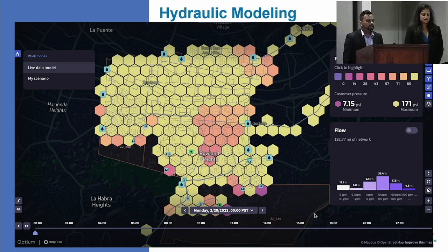So basically, first we don't even touch the actual SCADA system. We have a software that integrates to the historian, and we talk to you guys and check which tags have only read access and are not controllable. All these basic parameters, like pressure and flow, are only monitoring purpose tags. So we just integrate with those tags and get the data in.